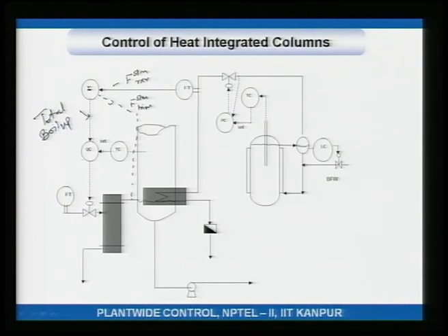How does this work? Well, if this steam rate goes all over the place, this signal goes all over the place, right? Now, because this guy is going all over the place, this Q controller actually takes this same signal.